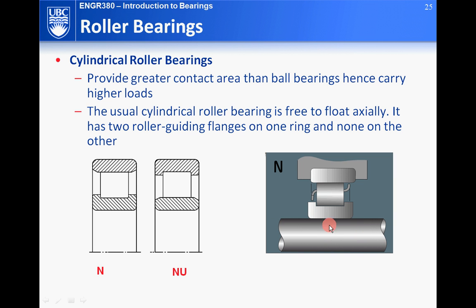If there is certain kind of, let's say, thermal expansion of the shaft, then what happens is the bearing here will be able to provide a certain capability of flexibility. A little bit of axial displacement is okay. So you go along this direction here. Is that good, right? This is what we call floating.